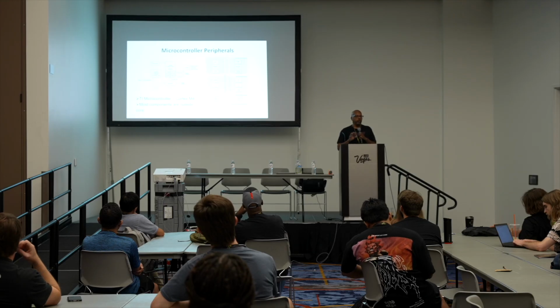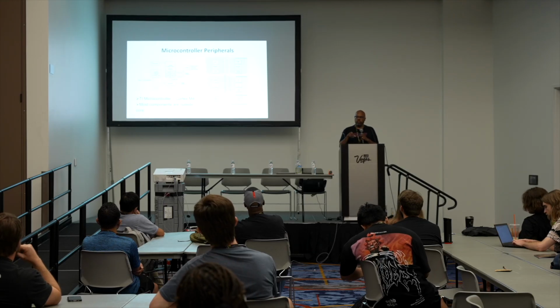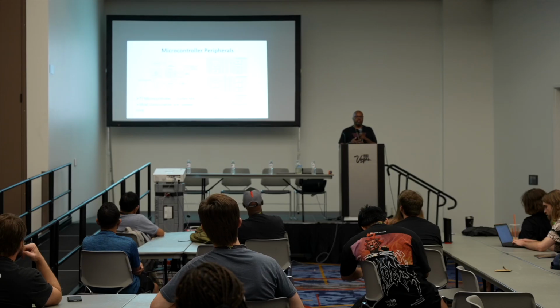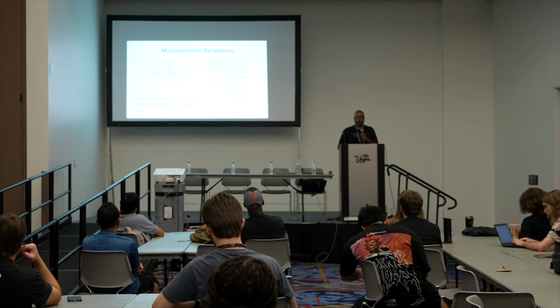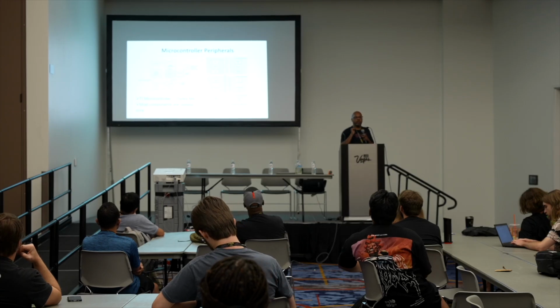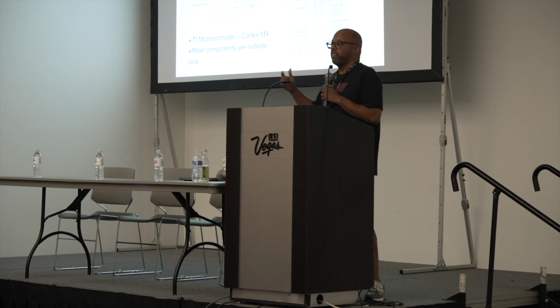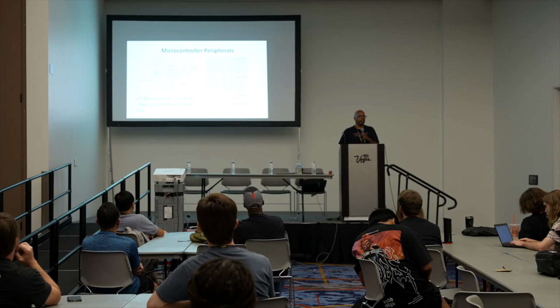But the main thing is this CPU is connected by these 2 long buses to all these peripherals, what are called peripherals. Now, these peripherals are what do interesting stuff on microcontrollers. They do all kinds of things, like general purpose I/O, right? The pins. If you want to control the pins, that's a peripheral. Or if you want to communicate by UART, that's another peripheral. Or if you want to do analog to digital conversion, that's another peripheral, right? All these blocks are peripherals, okay?